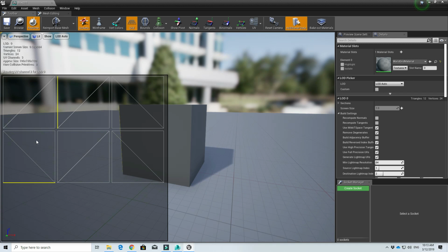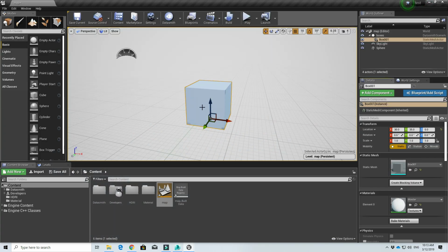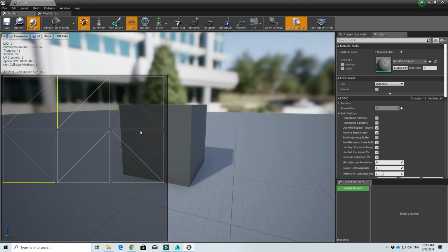If you recall what I discussed previously in tutorial 2, when the global illumination process started, where Unreal Engine built the light and calculated the shadows, it will store the shadow details of each object into its light map, which is what I'm showing you here. So it makes use of this light maps to store the shadow details.